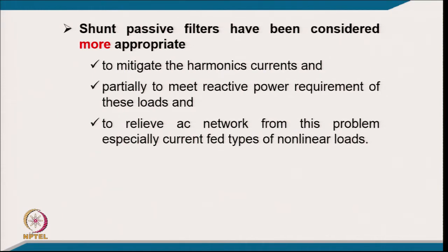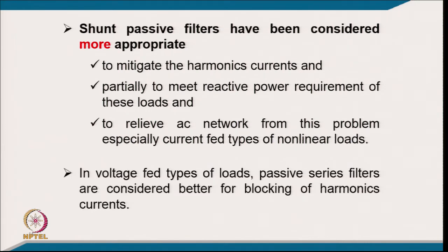Thyristor converters are used in DC drives, or to provide a DC current source for feeding a current source inverter, including the line commutated synchronous motor drive, large rating drives, typically of the order of 75 megawatt or 100,000 horsepower. So, they are used in all those applications with current fed kinds of loads.